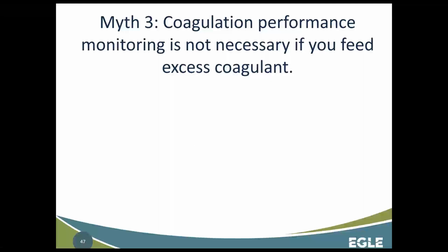Andrew, do you want to give us the answer on this one? Looks like most people chose option A. Yep, that's right. And I can understand folks that went for answer number 2. We do need rapid dispersion of coagulants, but the objective is to condition them for removal in subsequent steps. So glad to see people got that.